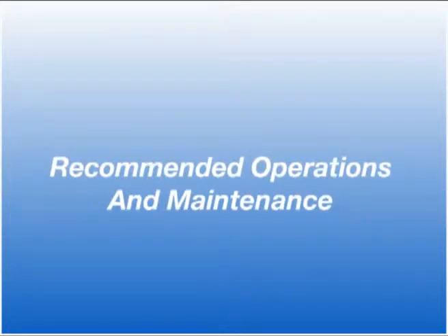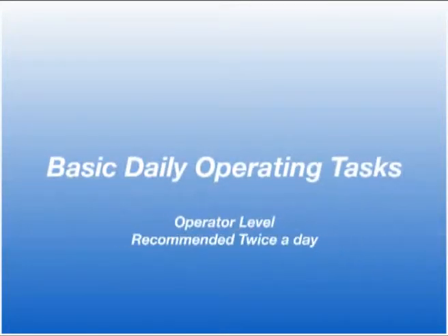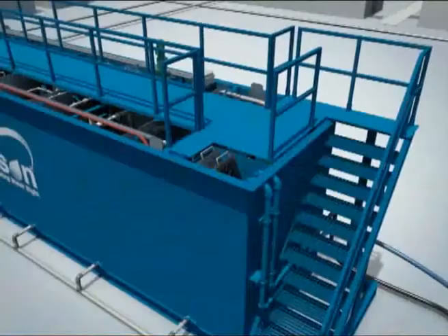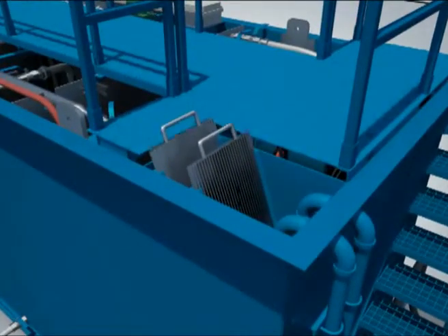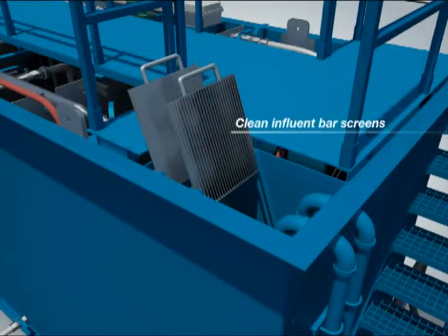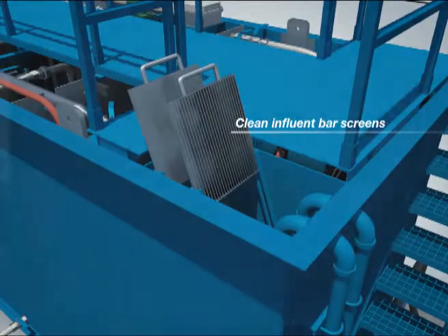Recommended operations and maintenance. Basic daily operating tasks. Operator level. Recommended twice a day. Clean influent bar screens with broom into trash can as often as required.